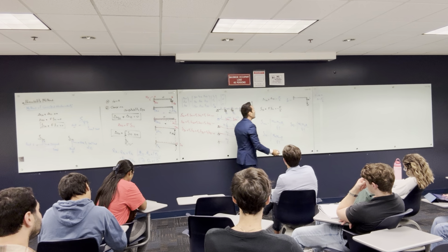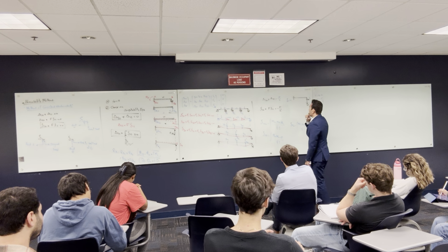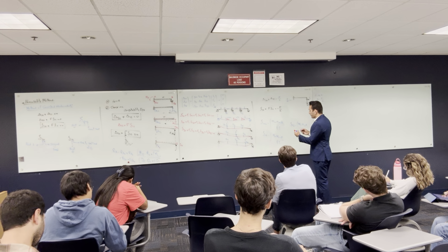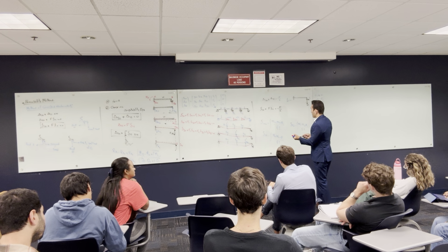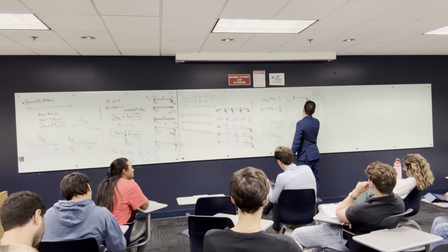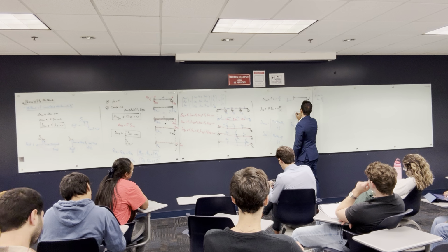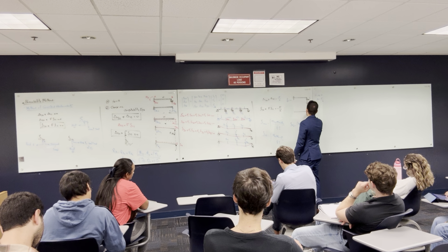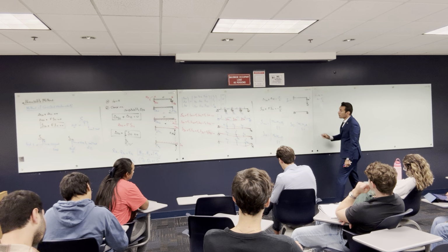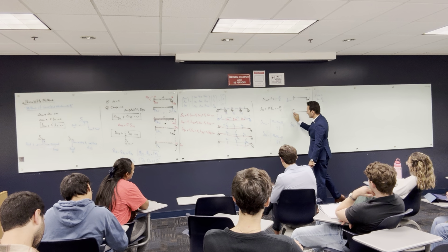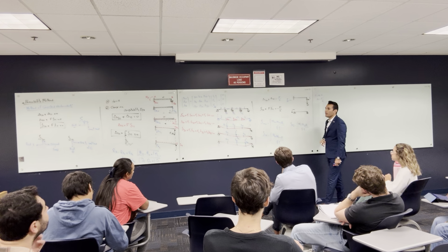Okay? Sometimes we solve the same thing with, let's say, this is not in the notes, so you might write it. Like if I have this and I have a roller, and you decided to make this a hinge. If you decided to make this a hinge, you release the moment like this, so you need to find the value of the moment.